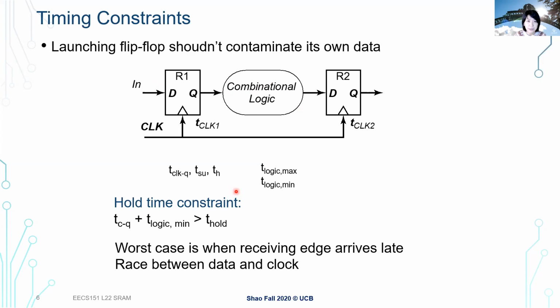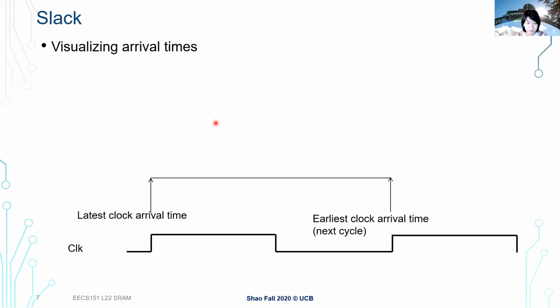So that's a quick recap of how setup time and hold time affect the functionality of your hardware. It's not only the critical path delay, which can be straightforward when we think about different logic gate delays. Now we have a lot more components here. We also need to make sure we have enough buffer so that the signal can be propagated correctly through our flip-flop stages.